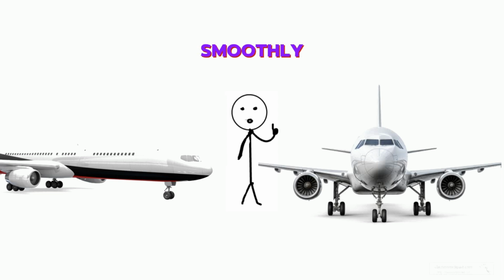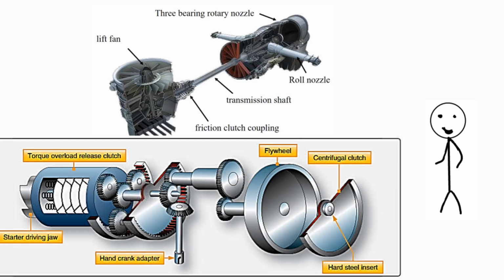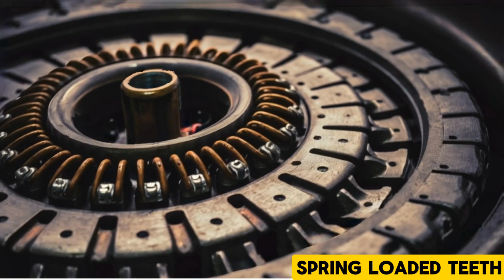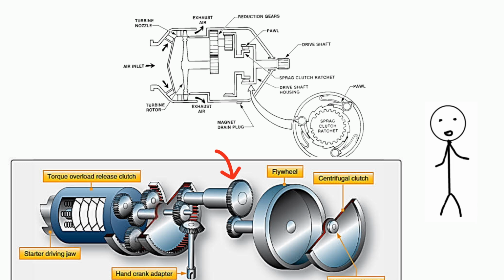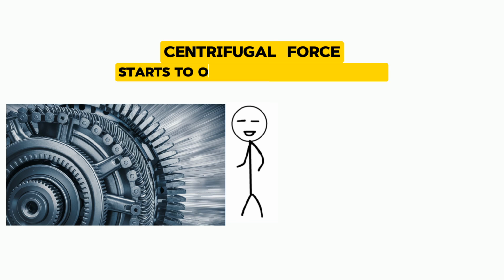Once the engine is running smoothly on its own, the next step is to disconnect the air turbine starter from the engine. This is done using a mechanical device called a centrifugal clutch, which is quite clever in how it works. This clutch has a central gear connected to the air turbine starter, surrounded by an outer gear linked directly to the engine. Inside this clutch are spring-loaded teeth. When the aircraft is at rest, these teeth engage fully due to the spring force, causing both gears to turn together.